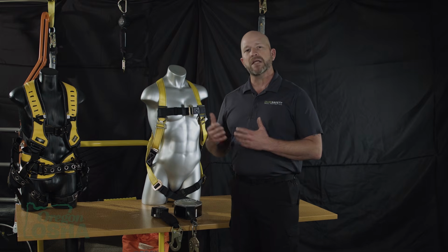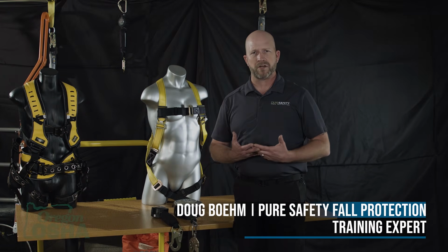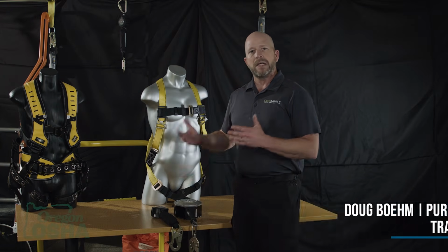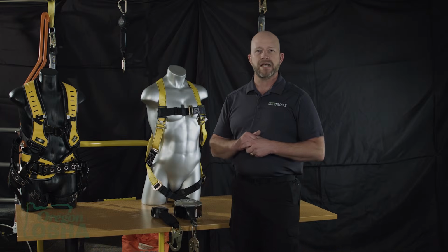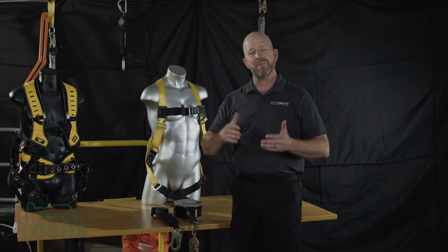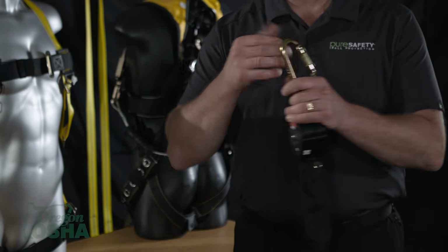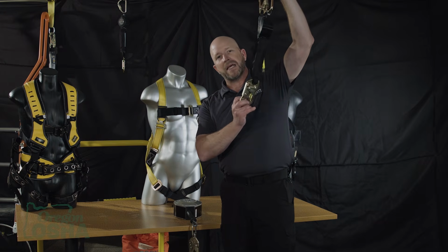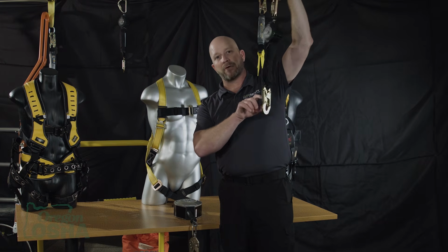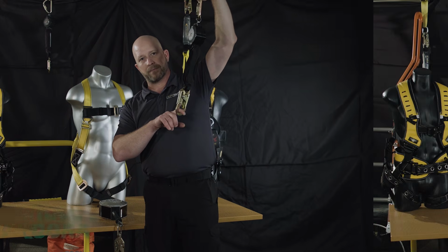The benefit to using an SRL versus using a lanyard is that on a lanyard system, although it is a fixed length, you have to fall the full length of it before deceleration occurs. Whereas a retractable has the ability to arrest the fall in a very short distance. Class A's are 24 inches or less, Class B's a maximum of 54 inches. The reality is that if a small block like this is attached to the anchorage and this is attached to the worker, if they begin to fall or accelerate, it's going to stop them in a very short period of time.